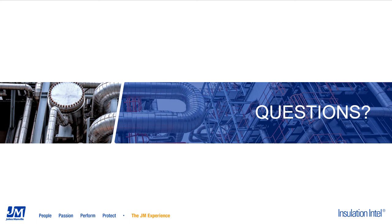Excellent, thank you. Scott, the next question is also for you, and that is, do you have any products for higher temperatures, say 2,300 to 2,500 degrees Fahrenheit? For that temperature range, you would definitely have to look at materials like a refractory ceramic fiber or possibly a very high temperature ceramic fiber blanket. We do not have anything rated for anything higher than about 1,700 degrees Fahrenheit, which is our Super CalTemp 1700 product. All right, thank you.